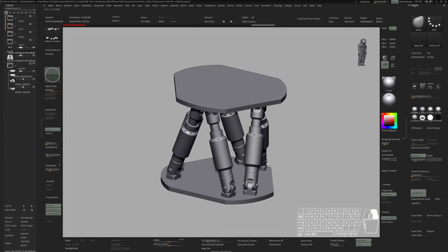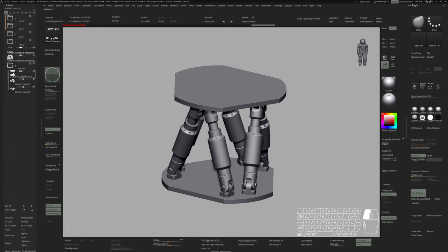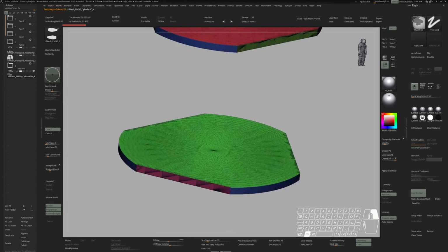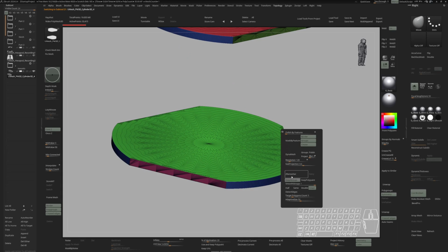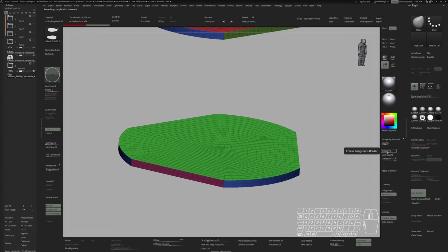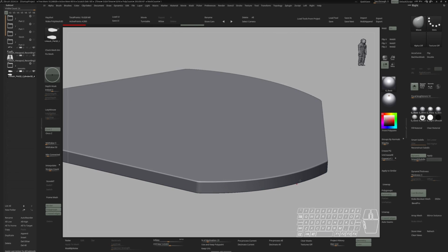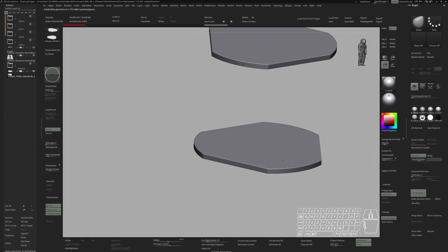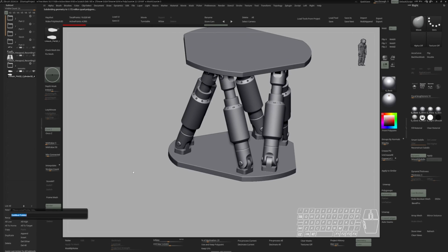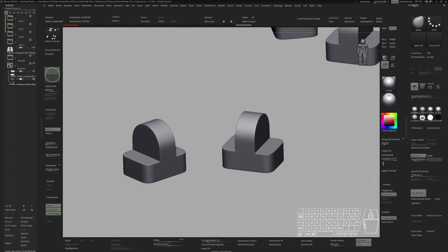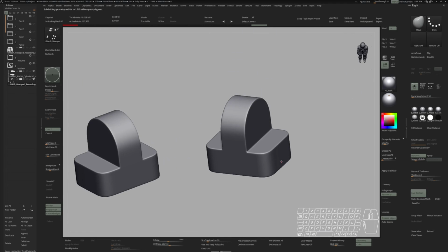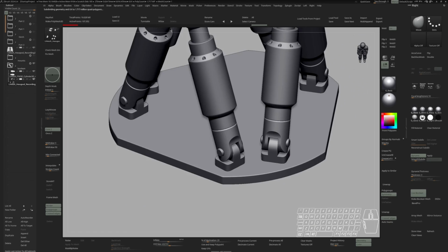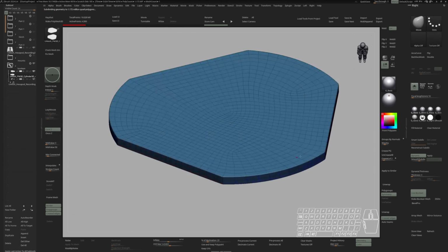And now I would like to do 2 Boolean operations. So first I'm going to Boolean the top and lower mount and simply do a ZRemesh with keep groups and smooth groups off. Turn on crease polygroups, dynamics, until we get a nice result like that. Create a new folder, let's do this Boolean for now. Put these sockets in, and let's turn off crease level here, so we get a nice bevel. They have one polygroup, which is good. Give this one polygroup as well.